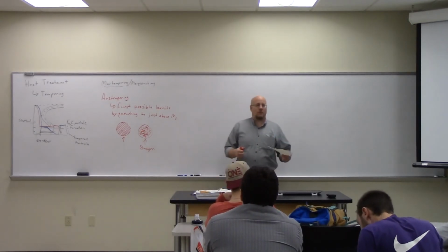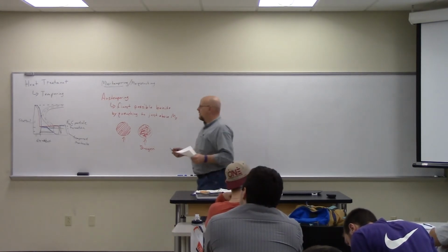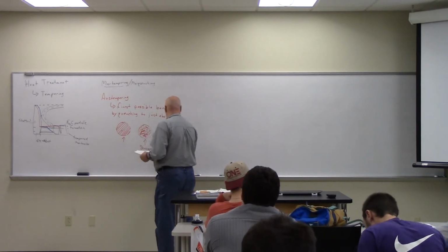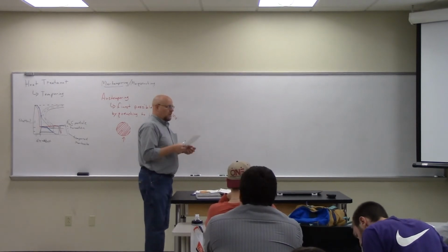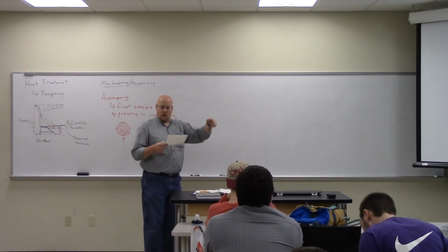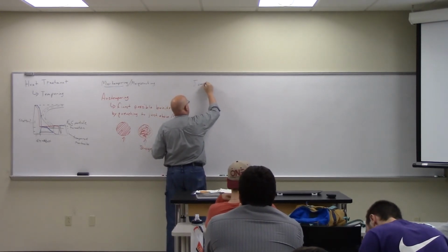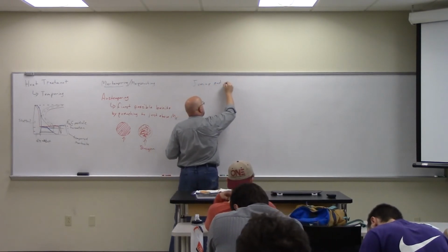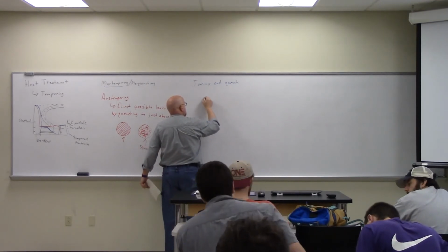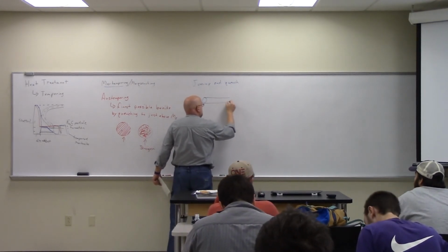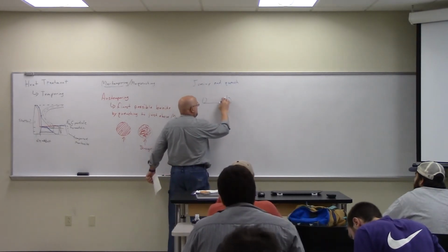So, in terms of characterizing the performance of these things, the way that we characterize how different quenches behave in terms of the material properties is use a process called a Jominy end quench. So take a Jominy bar, which is nothing but a 1 inch by 4 inch round bar, and oftentimes there's a flat machined on the top surface.